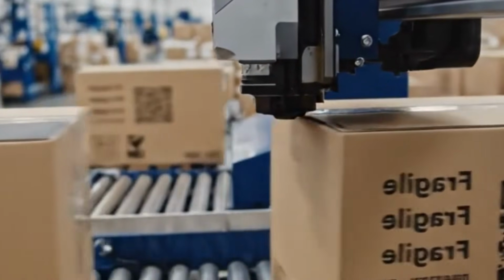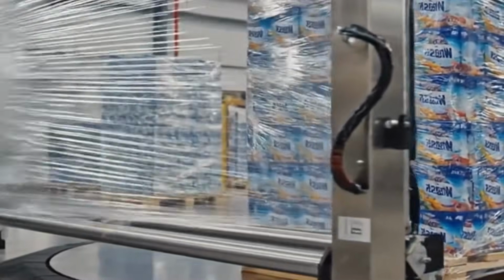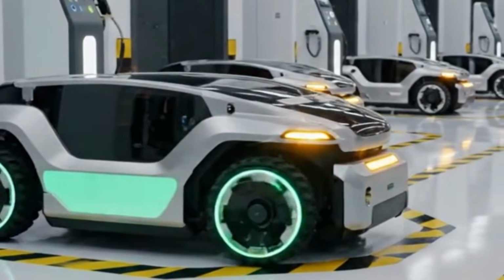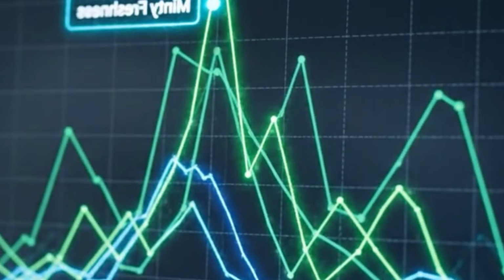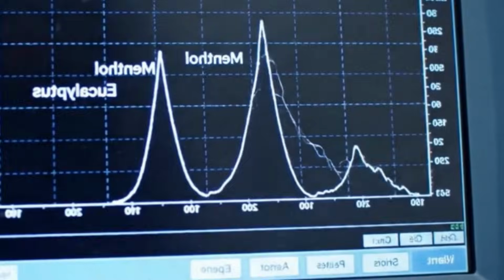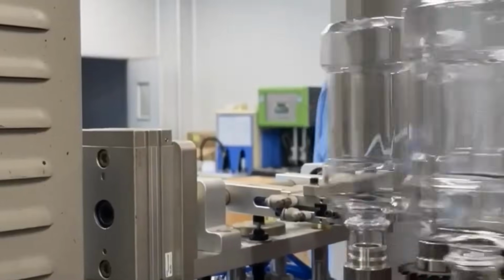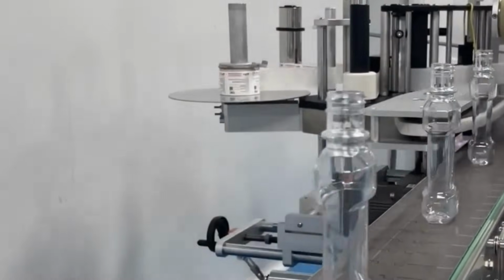The final mouthwash formulation is adjusted for pH. Aqueous solutions of sodium hydroxide or citric acid are prepared in auxiliary tanks and dosed using digital peristaltic pumps. pH is continuously monitored by inline probes to maintain a range typically between 4.5 and 7.0, depending on the active ingredients and flavor profile. Anti-foaming agents are optionally added during the final mixing phase.